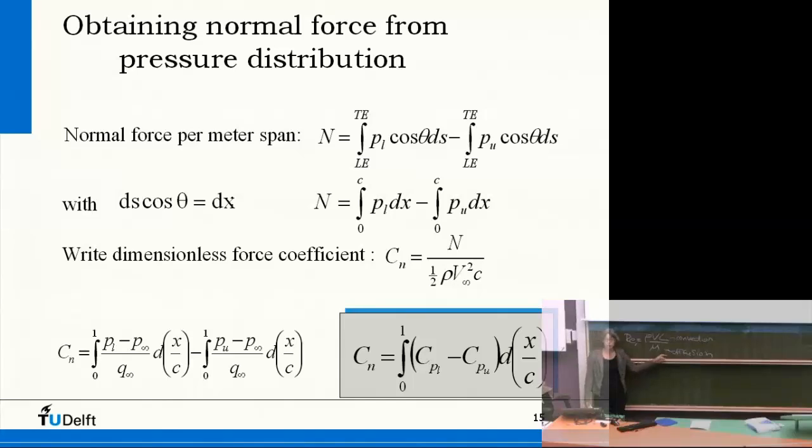Well, a high Reynolds number, an aircraft flying, so say Boeing, is at millions, order of millions. So very small diffusion phenomena, very strong convection phenomena. What does that mean? Thin boundary layer. Inviscid flow, you can assume if you have attached flow outside the boundary layer. So convection is dominant. Yes?